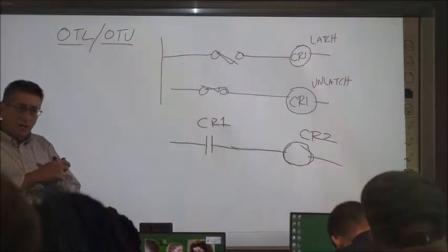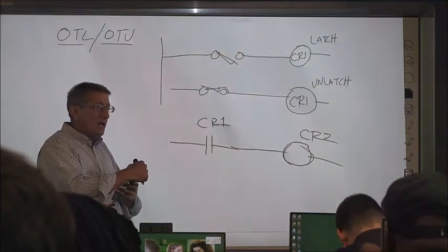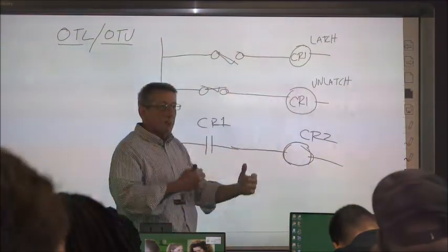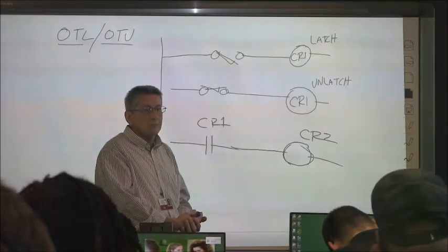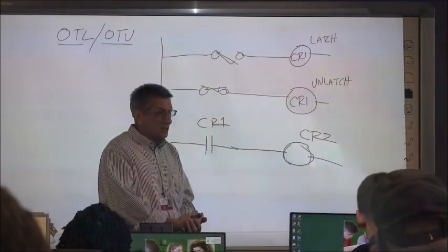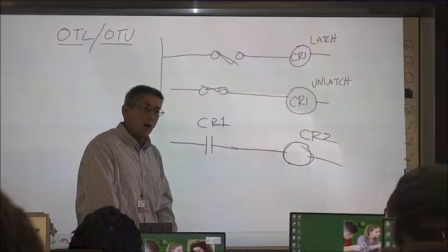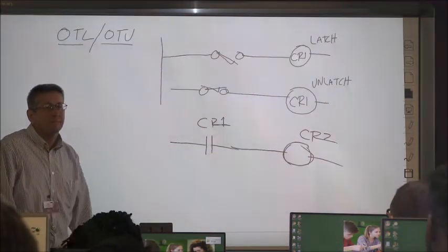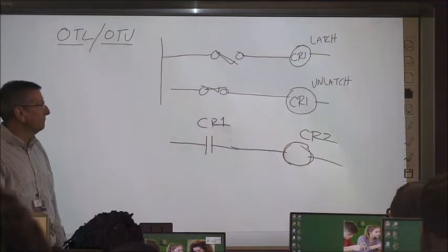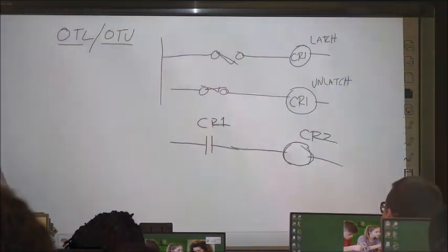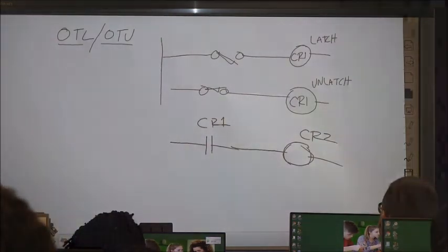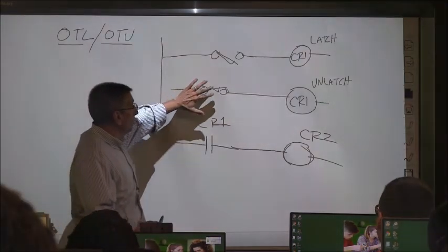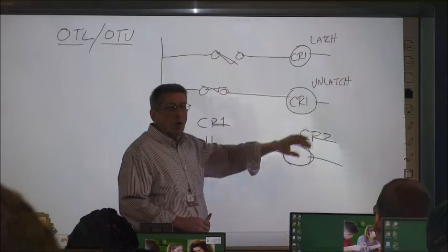And here's the key to this thing too. Once you latch up, let's say the power goes down. It stays latched in. Power comes back up, it's still latched up. So no matter what you do, that stays closed? Yes, until we energize the unlatch coil.